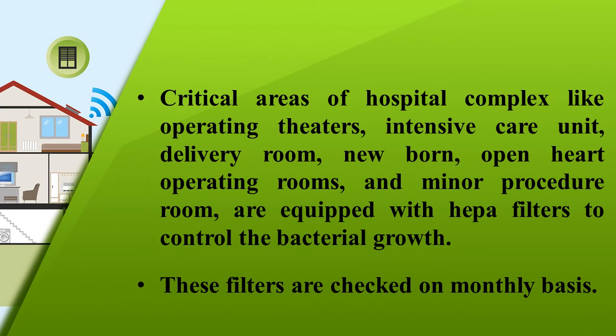Some critical areas of a hospital complex, like operating theaters, intensive care unit, delivery room, newborn, open heart operating rooms, and minor procedure rooms, are equipped with HEPA filters to control bacterial growth. These filters are checked on a monthly basis.